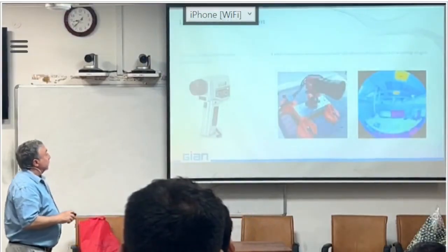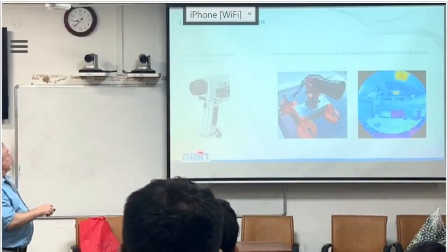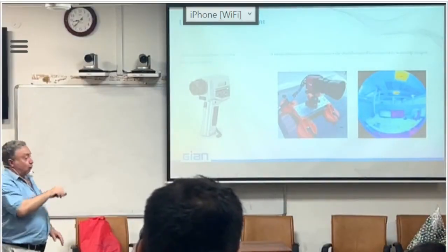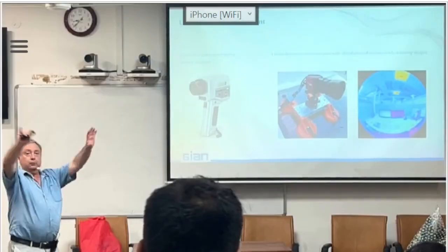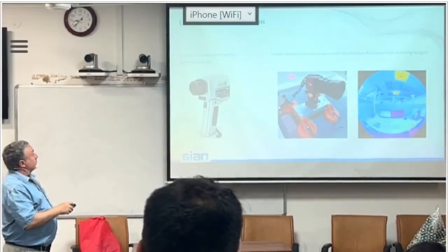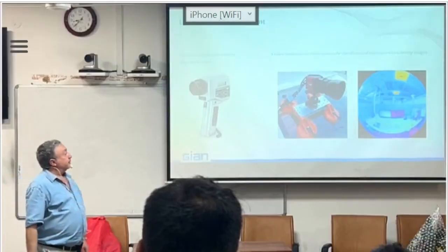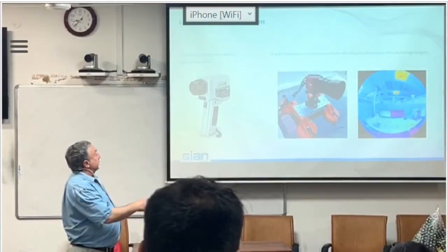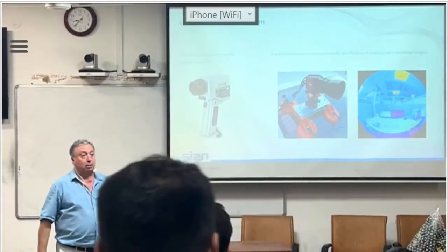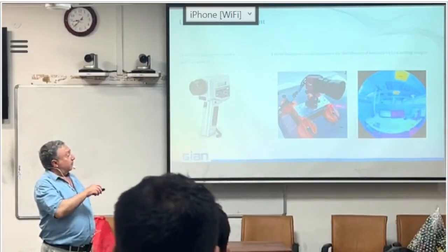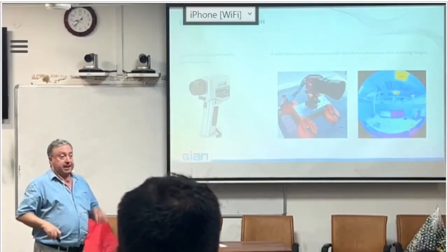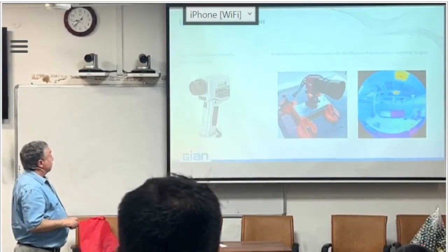How do we measure that? We measure it either with luminance meters, which are this kind, if you want to measure one point. If you want to measure the full space, you can use video luminance meters, which are cameras or photo devices that can get the luminance everywhere in the space with one shot.